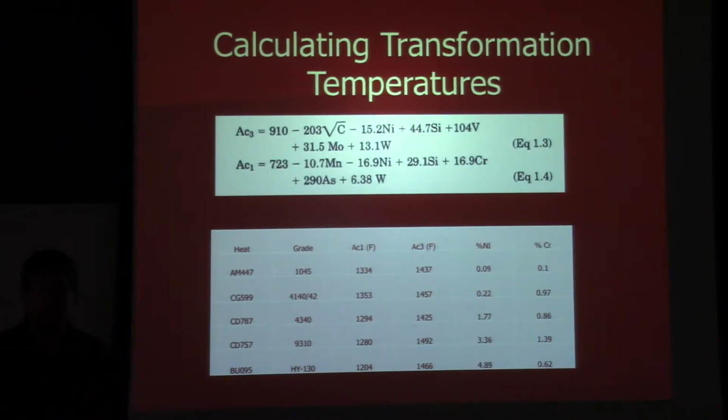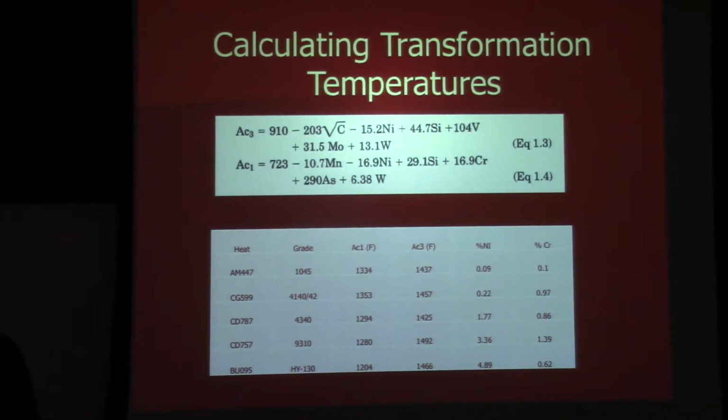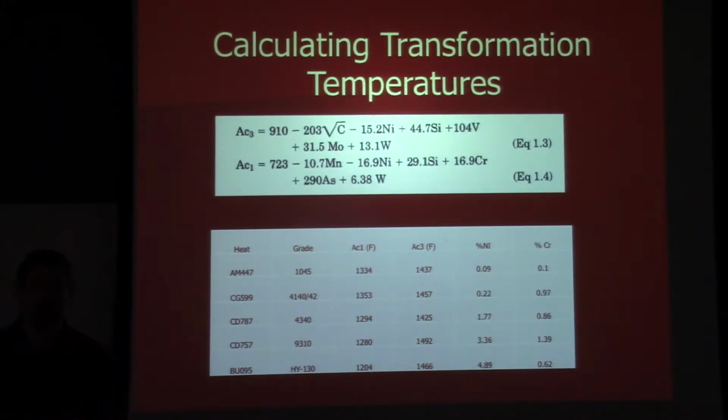That's why on the phase diagram, when you have iron carbide, it's at 6.67%. But if you look at Fe3C, it should be 25%. But because the number of moles is dependent on the weight, and carbon is such a lower mass element, it's at 6.67% by weight.